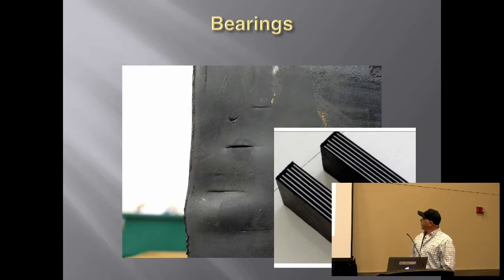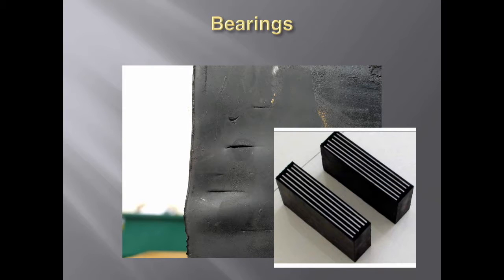Okay, so this is what the elastomeric bearings look like. There's vulcanized rubber in between each steel plate. One of the things that we're concerned about is when the welders are out there and they start welding these girders down, that they don't exceed 200 degrees. Because at that point, the elastomer will lose the vulcanization to the steel plates, and they'll separate, and then basically we have another failure in the bearings itself.